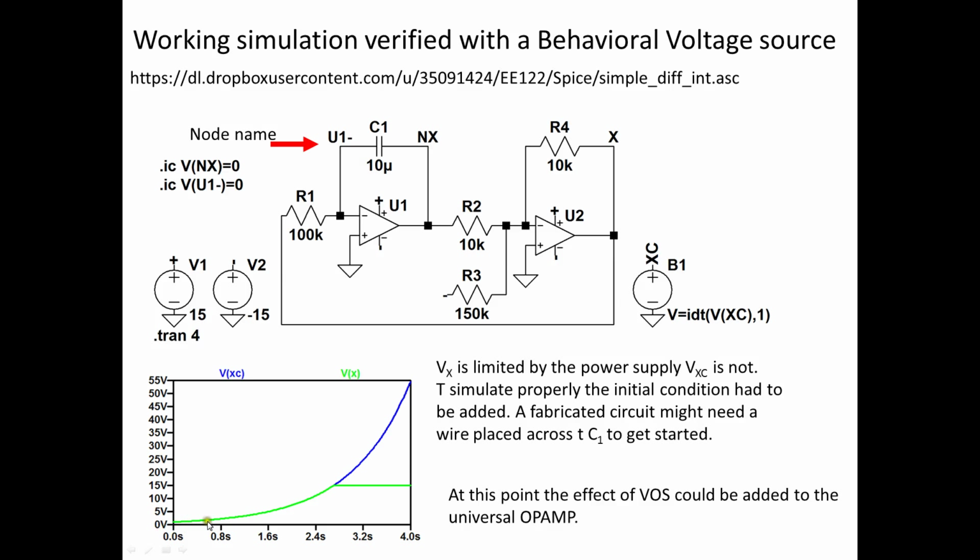And you can see that it matches pretty well right up until about the power supply, in which the op amps saturate, but this behavioral model doesn't. I could add V offset problems or other things to simulate, but not going to do that at this time.